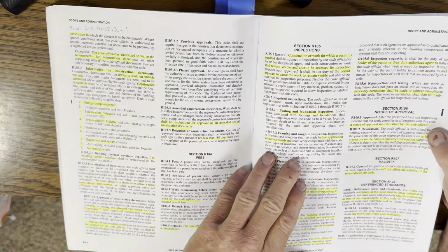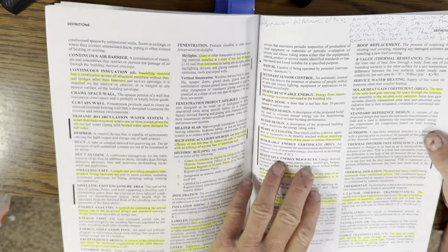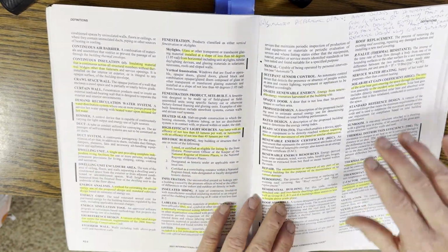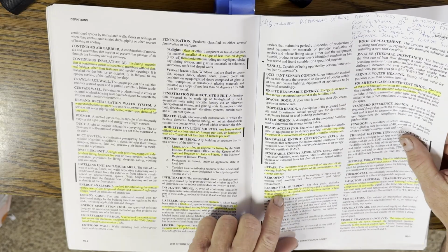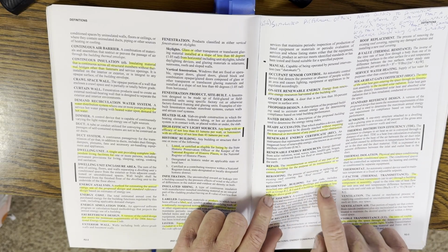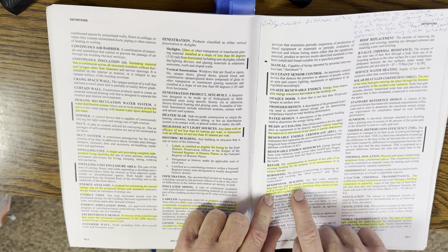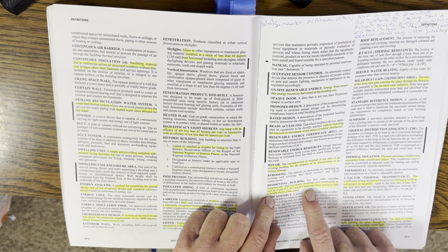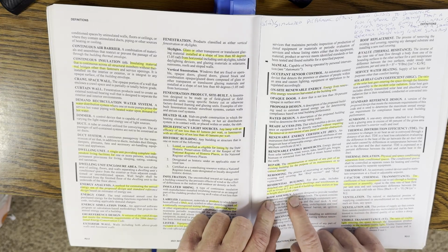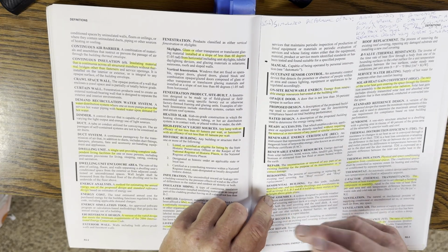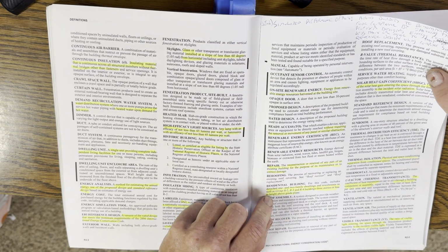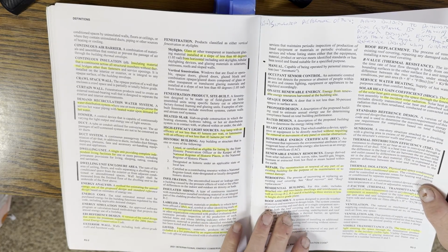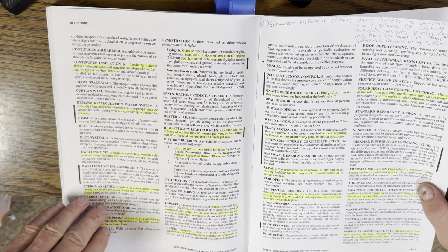So if you just jump over to the actual definition in chapter 2 of residential, it'll show you what the definition is. So in this case, here's the definition: residential building. It's detached 1- and 2-family dwellings, townhouses, groups R2, R3, and R4, 3 stories or less in height. So don't let that catch you. I think one of the questions of the 4, besides the one I already gave you, was like there's a couple 4-story buildings, things like that. There's even an assembly occupancy in the list, which was kind of lame.